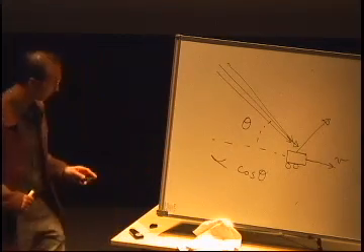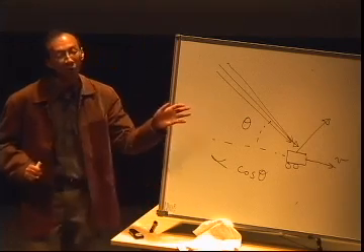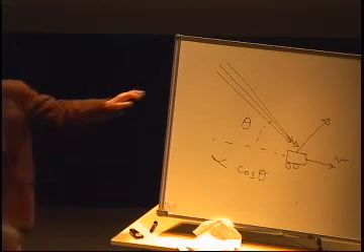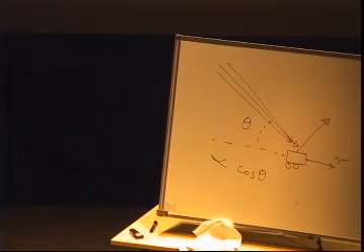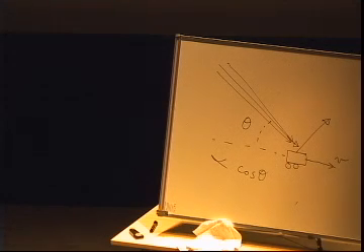Why is this important? Because depending on what kind of environment you have, you may have very limited Doppler spread, very limited angular spread. Imagine I have a base station, a tower. You're looking at very far away, and there's very little local scattering around you. Then the angular spread is very small. If you're on the ground and there's a lot of stuff around you, like my office, a lot of clutter, then there's a lot of angular spread. So in different scenarios, you have very different angular spread.